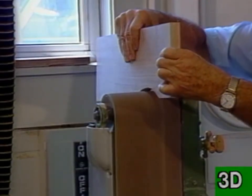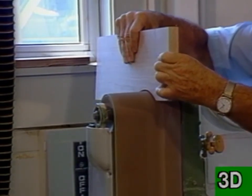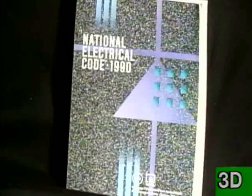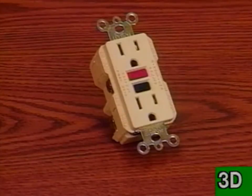Another precaution is to never operate electrical equipment outdoors or in wet conditions unless the circuit is protected by a ground fault circuit interrupter. The National Electric Code requires that all outdoor outlets and outlets in wet areas such as kitchens and bathrooms be protected by a ground fault circuit interrupter. Ground fault circuit interrupters sense short circuits and immediately interrupt the flow of electricity should a ground fault occur.